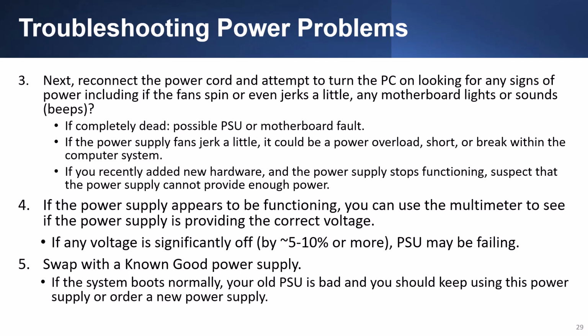If the power supply appears to be functioning, you can use the multimeter to see if the power supply is providing the correct voltage. If any voltage is significantly off by 5 or 10% or more, the power supply unit may be failing.